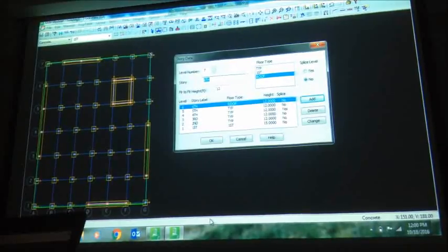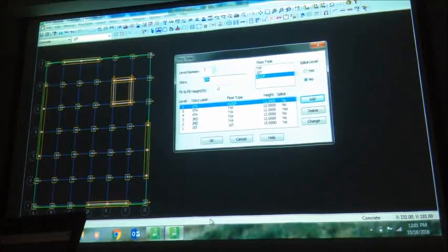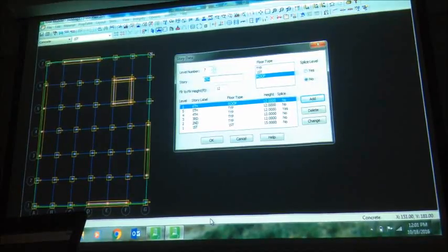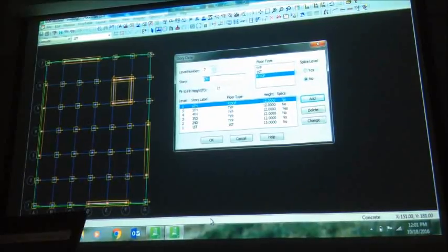Quick question. Yes. After how many feet do you need splicing? No, usually I try to give 3 floors as a single. For a concrete building, you do not need to give any splicing. If you want, you can have the same column size. I mean, obviously, after 3 floors, the loads will not be that high, so that's why I changed it. But in steel, yes, you have to have at least 3. After 3 stories, you have to have the change, because that's where you're splicing. Steel columns cannot come like 60 feet.